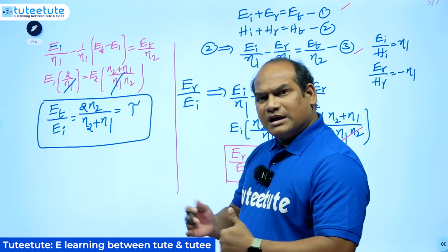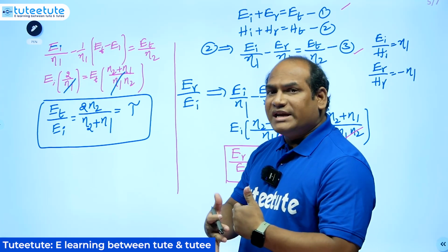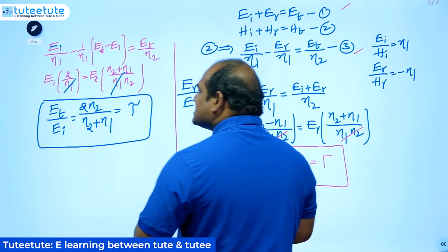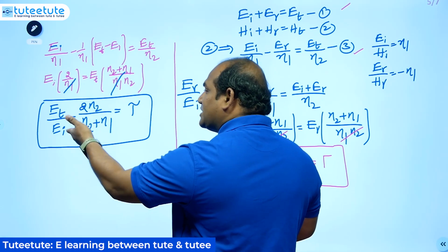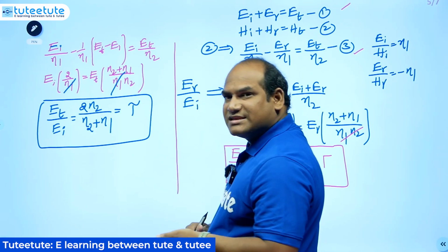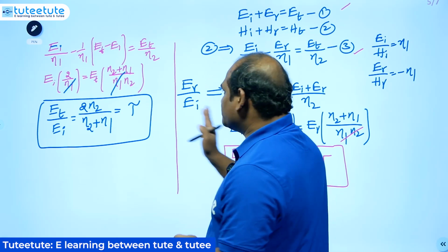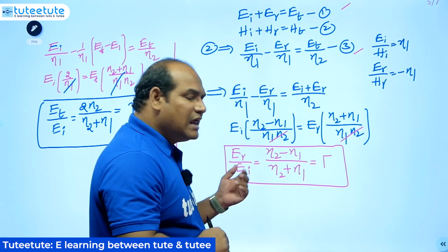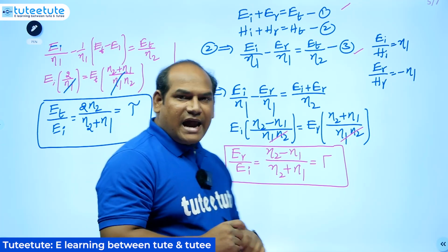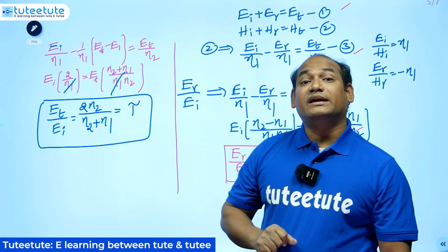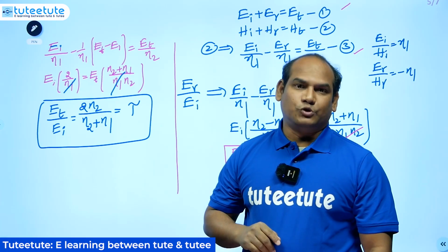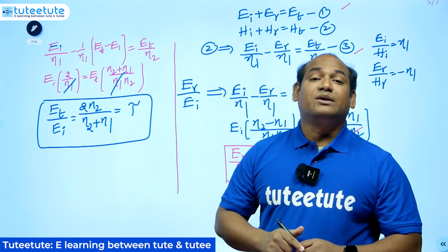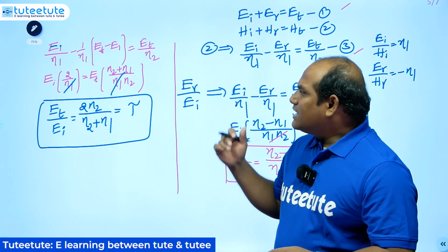So now for the normal incidence case, when you incident the electromagnetic wave normally to the surface, or to any plane, to any boundary, then how much electric field can be reflected back, or how much electric field can be transmitted into the other medium out of the given incident electric field, is given by these two. By having this reflection coefficient in terms of the electric field, we can tell how much is reflected back, and using this transmission coefficient formula we can tell how much can be transmitted into medium 2. These formulas are given in terms of the impedances only. Very simple thing.